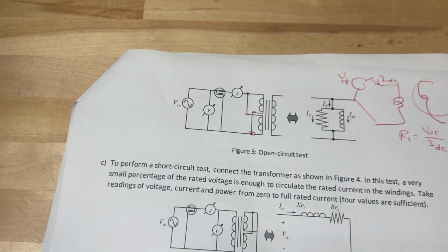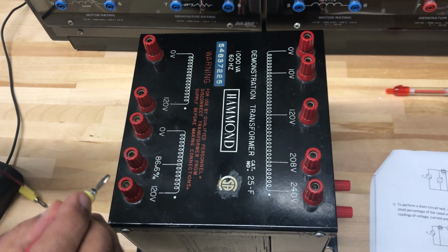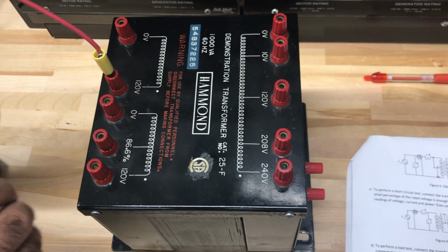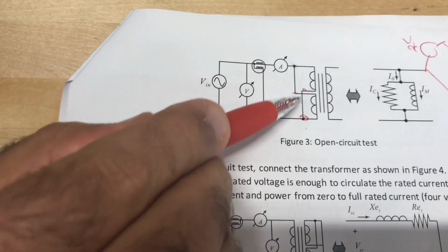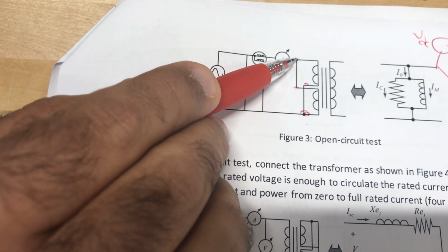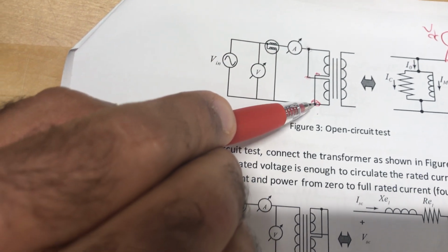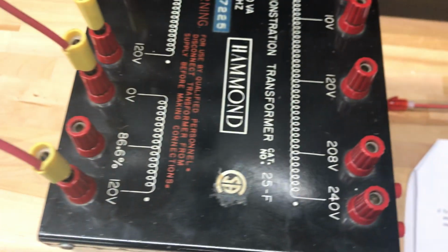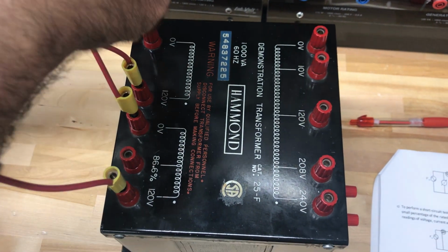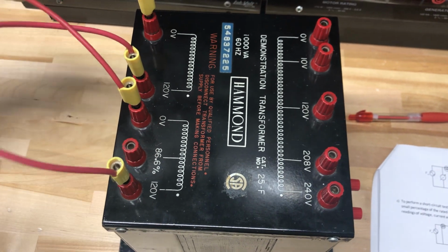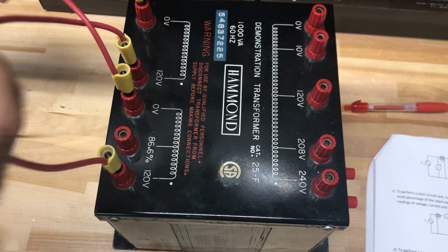And then the supply, I'm going to connect it. So the first step is I will connect these two windings because I'm going to feed the voltage here. So I'm going to connect this guy, like what he did, to this guy, and this guy to this guy. This is what he did here, as you are seeing. So he connected this end by this end, and this start by this start. Then the supply will be between this point and this point. So my supply will be through one of these two. So it will be between this and, for example, this one.